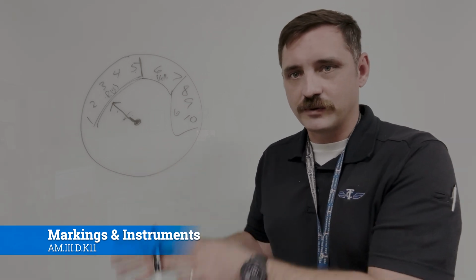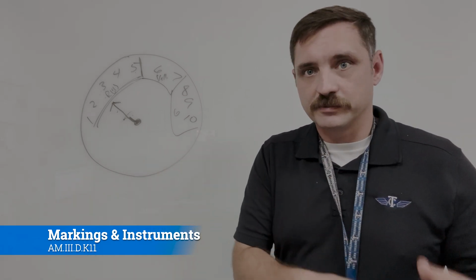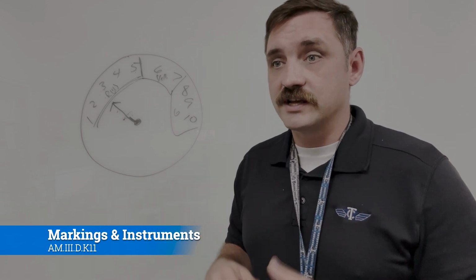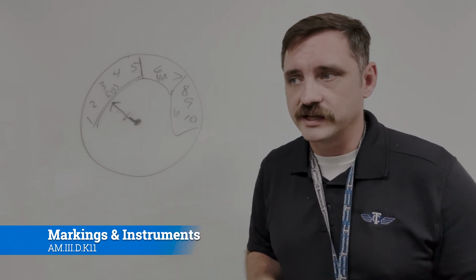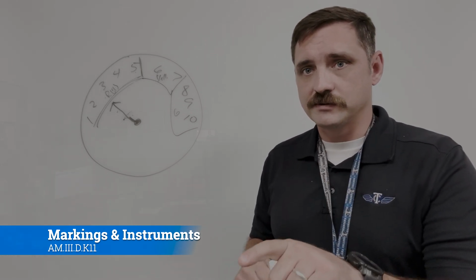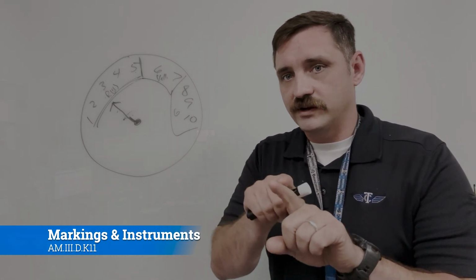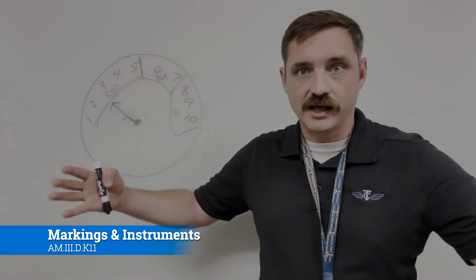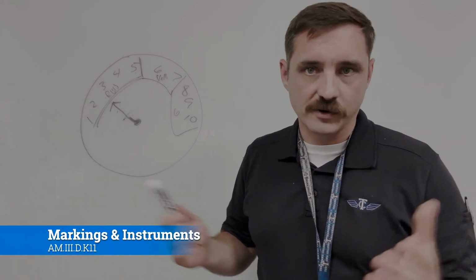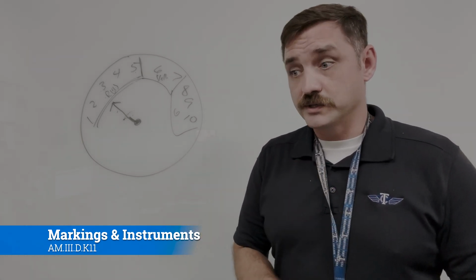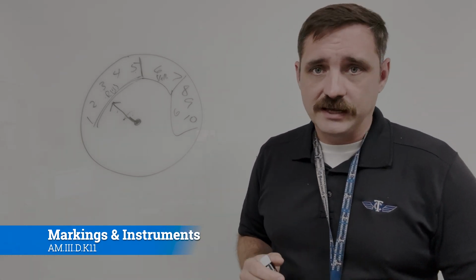Another way to go about doing it is simply to do what they call robbed parts forms, where you can take one off of one airplane and then install it on this airplane and see if that works. That comes with its own challenges. It's legal to do, and it's common practice with some certain things. The only trouble with that is that if that gauge is the problem in the system, you run a chance of introducing a problem to a whole other aircraft, and you also have two aircraft in the same setup, side by side, that are both not being actively used. So there's challenges with every single one of those. However, it can be done.